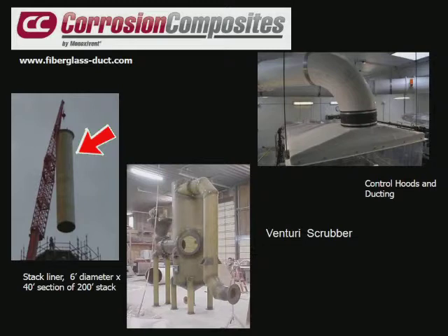And when they did that, the old brick and concrete couldn't take the sulfur condensate that would occur in the stack. So we built these liners that would drop in, and the lower section had a base that anchored, and then the next sections had a big funnel with an 8-inch socket.